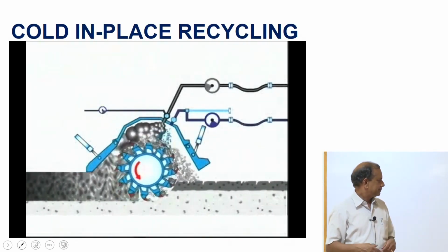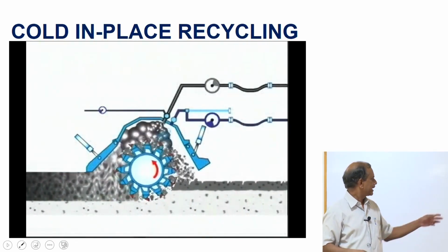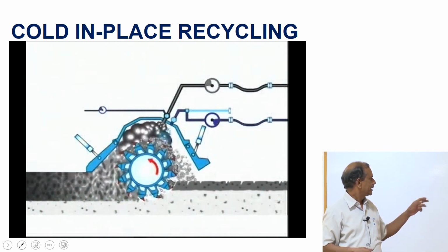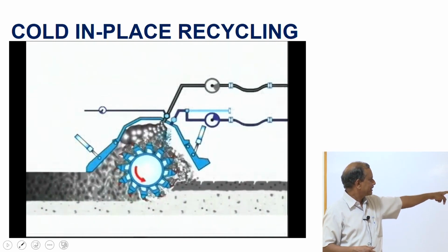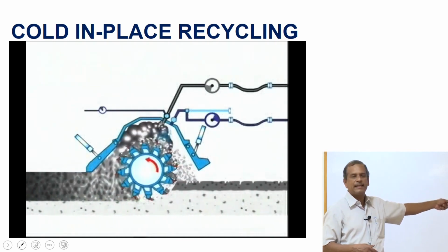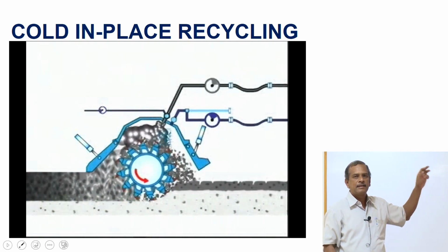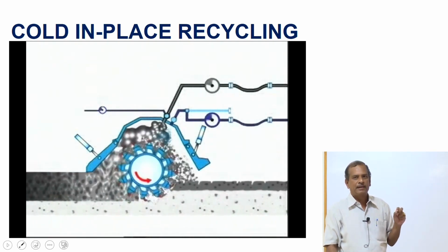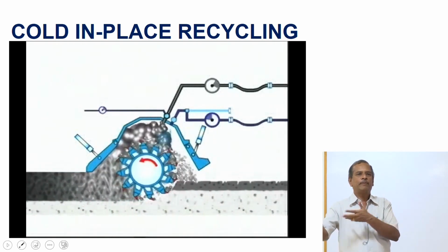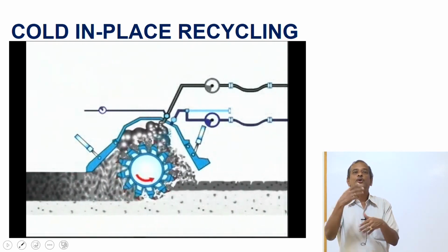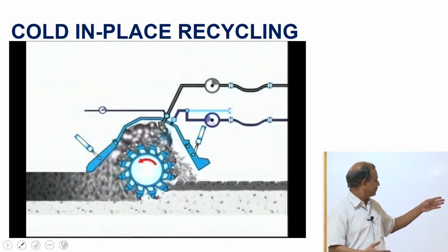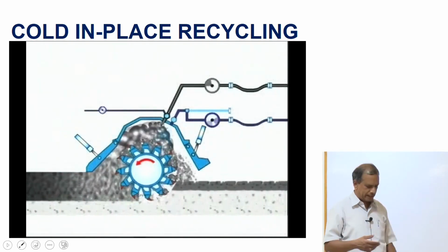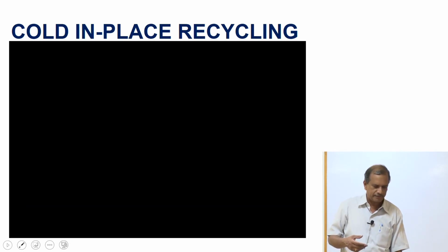I mill the material and inject the foam bitumen. So, this layer is called a bitumen stabilized material, or BSM. I have not thrown out the whole deteriorated pavement material, I am trying to reuse it again. Because the material has deteriorated, I am trying to strengthen the material properties by using foam bitumen. I can reduce the thickness of the layers.